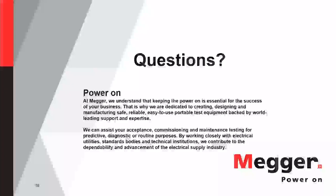The one place where I generally recommend a digital one for sure is on your rotary transducers. Because the problem when you use an analog rotary transducer, it's a resistor. You can't keep spinning this thing around. You actually don't have a full 360-degree movement. And so it goes from 0 to 357 degrees, and then it resets itself. So if you're not paying attention and you hook up this rotary transducer, and it's right at, say, 340 degrees, and it's going to spin and go through that 357 and reset, your motion's going to be bad.